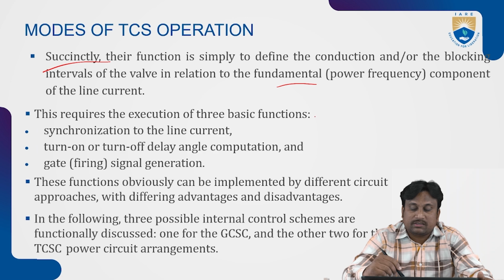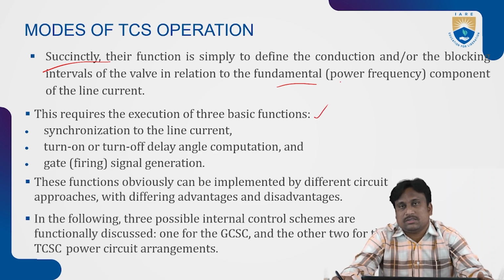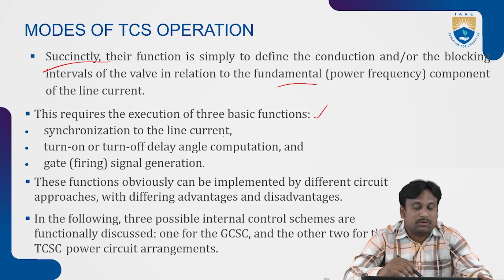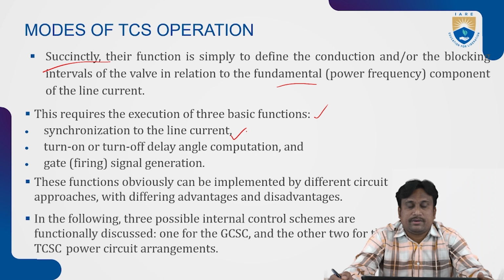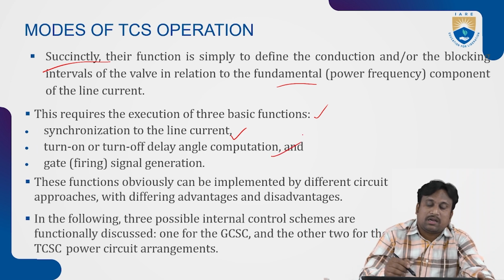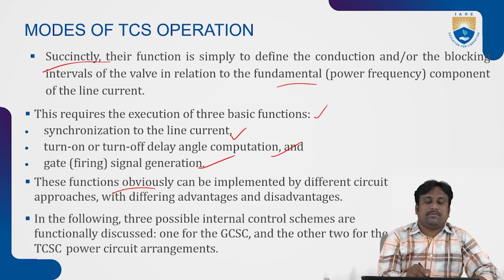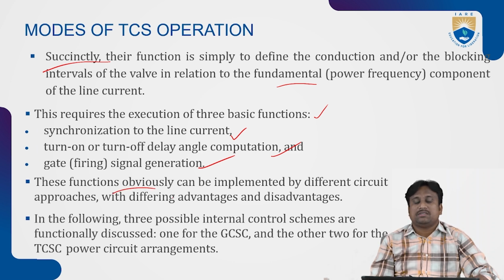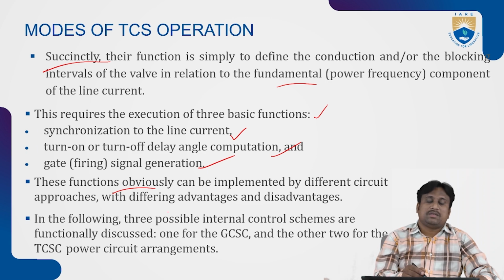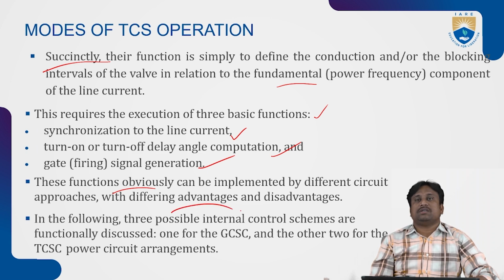So this requires the execution of three basic functions: synchronization to the line current, turn-on or turn-off delay angle computation, and gate firing signal generation.